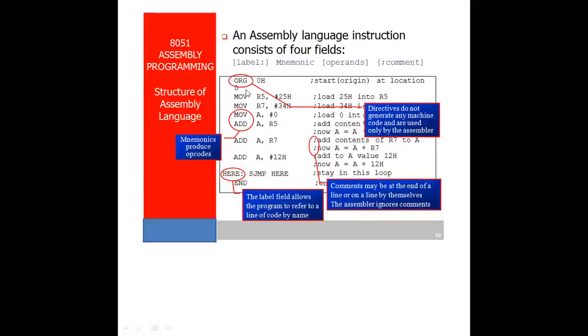So the lines that we are finding in this program, that ORG 000 hex and the END, actually these are the software directives. Whenever I'm trying to burn the program inside the ROM memory of the microcontroller, I have to write these 2 lines to start at this location 000 hex and end the program, because there is no such instruction available inside the 8051 microcontroller instruction set. That is ORG 0000 means origin 0000 hex, and the END. Actually, these are the software directives.